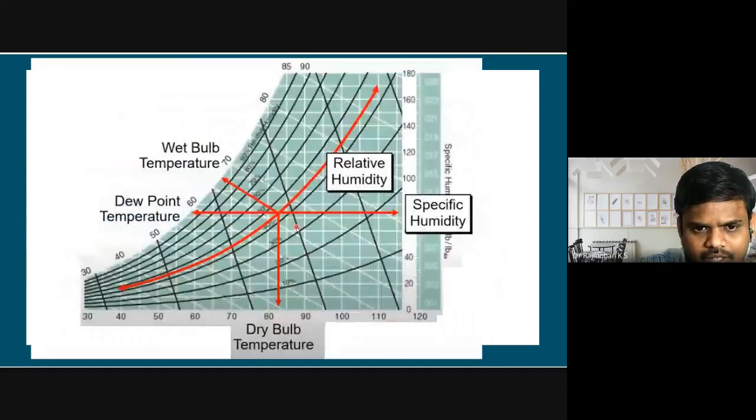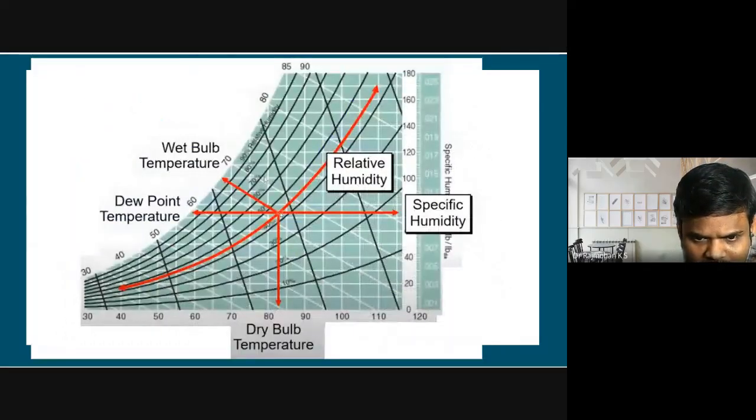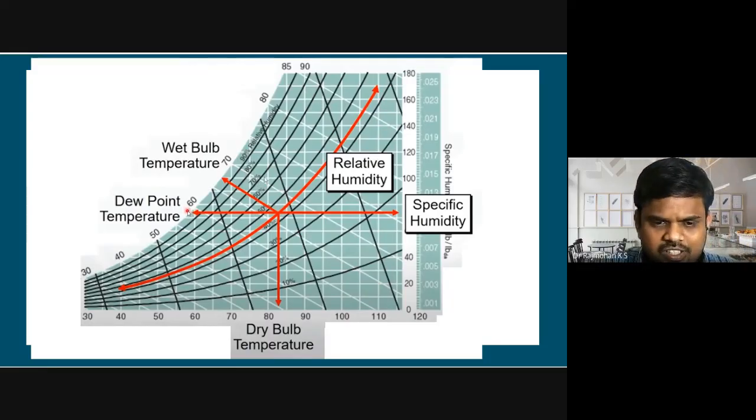Okay, thus we have seen different points. Here we are going to get the dry bulb temperature. From this same dry bulb temperature, if you keep saturating without changing the humidity, the percentage saturation increases, and at 100% saturation what we get is the first condensate. The humidity is not changed, but we have reduced the temperature such that the air is saturated with water vapor.